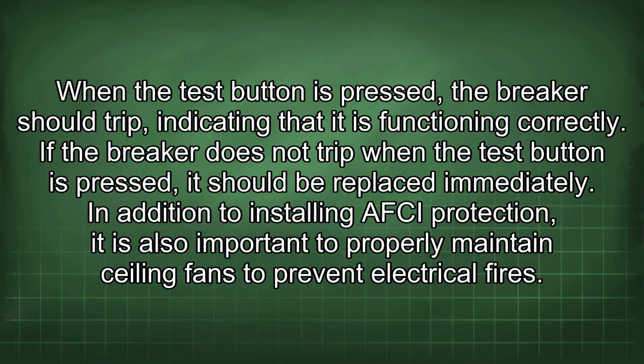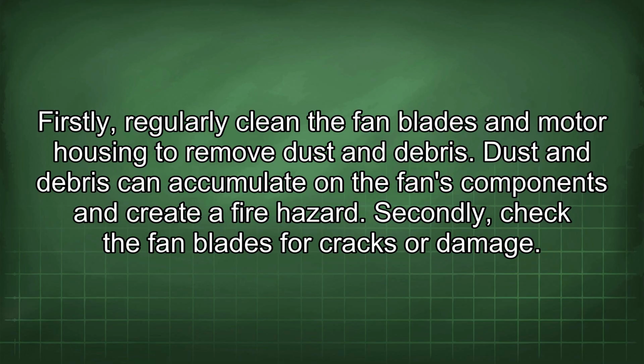In addition to installing AFCI protection, it is also important to properly maintain ceiling fans to prevent electrical fires. Firstly, regularly clean the fan blades and motor housing to remove dust and debris. Dust and debris can accumulate on the fan's components and create a fire hazard.